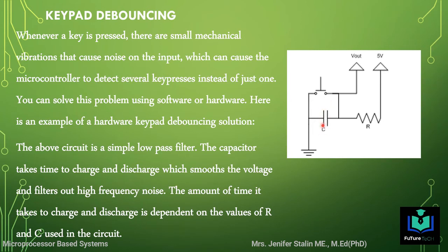So as the capacitor charges as well as discharges, the noise which is caused due to the mechanical vibrations may be removed by means of the low pass filter. This is one of the techniques, called hardware keypad debouncing. Another technique is called software keypad debouncing, where a particular delay of time is initiated in between the keypad.